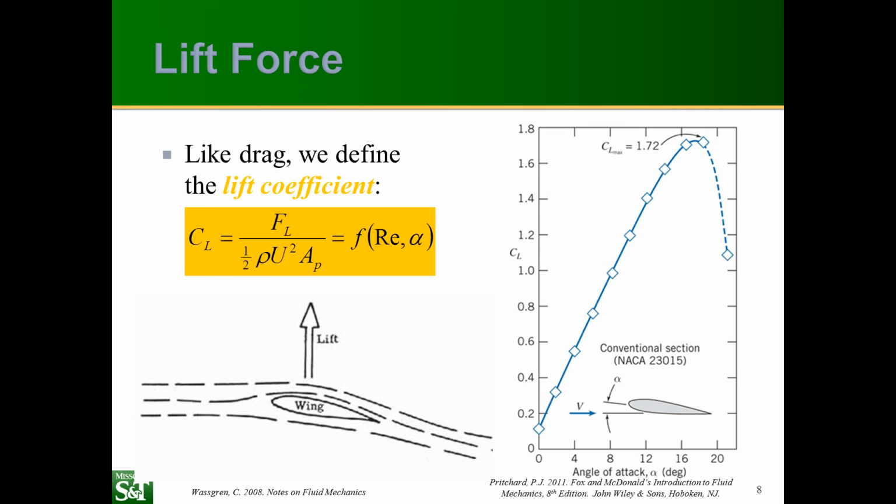So the lift is created essentially from inviscid flow analysis, Euler's equation. Essentially the air on top of the wing is moving faster than the air on the bottom of the wing. Therefore, it has reduced pressure, and that pressure produces a force that moves upward. So it's basically generated from circulation of the flow around the object.